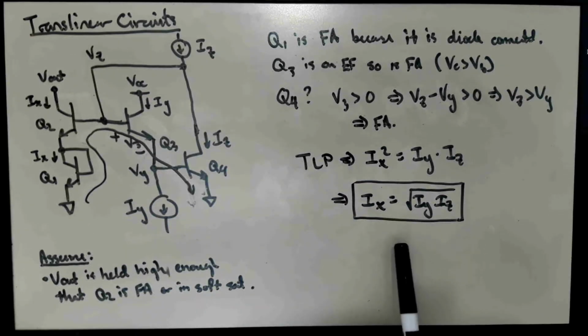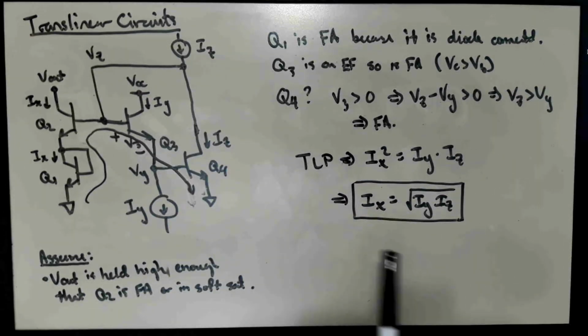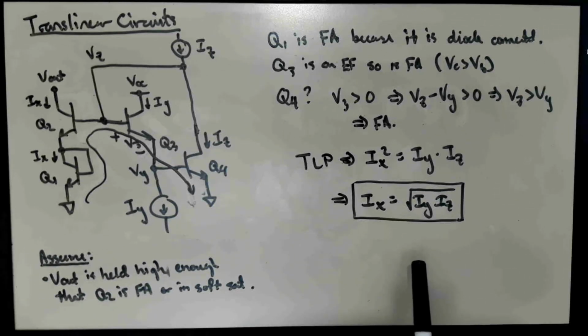In point of fact, the last circuit and this circuit are formally inverses of each other. They implement inverse functions of each other, and if you were to take the output of the one and feed it into the other one for the same value of the other current, you would just get a fancy current mirror. It wouldn't be a very good way of implementing a current mirror compared to the way that we talked about a couple of times ago, but that would give you sort of the identity function. So that's our second example of something that you can do with this loop.